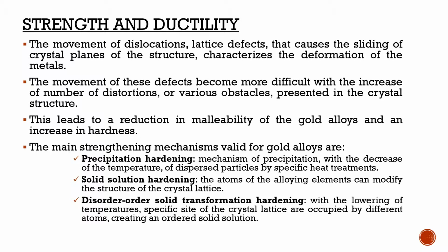And moving on, strength and ductility. The movement of dislocations, lattice defects that cause the sliding of crystal planes of the structure, characterizes the deformation of the metals. The movement of these defects becomes more difficult with the increase of the number of distortions or various obstacles presented in the crystal structure. This leads to a reduction in malleability of the gold alloys and an increase in hardness. The main strengthening mechanisms valid for gold alloys are